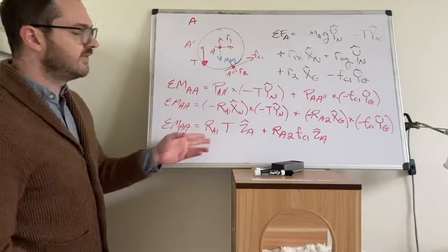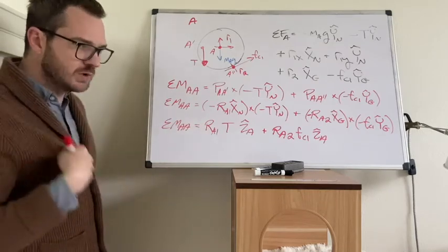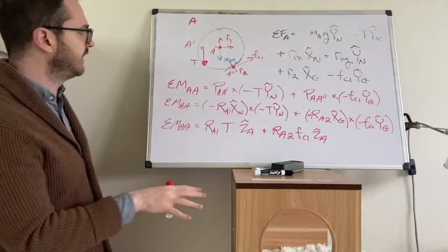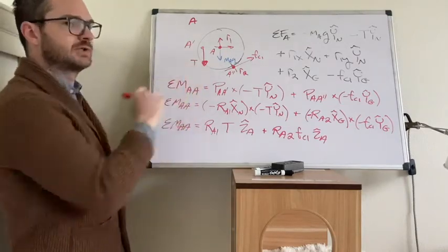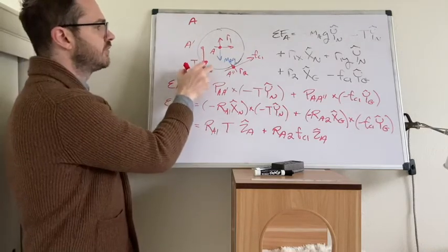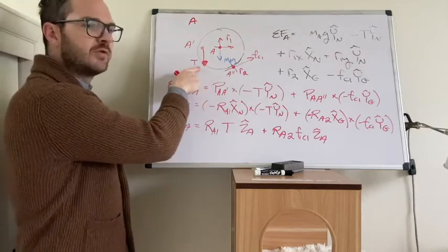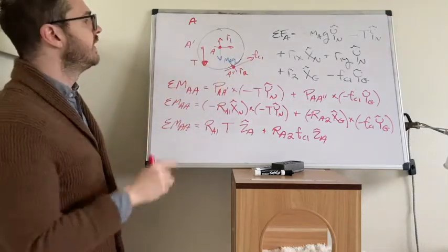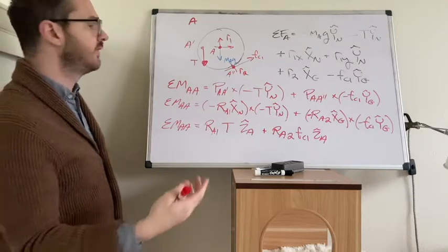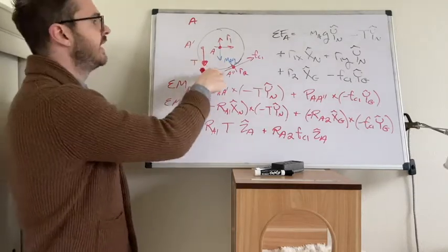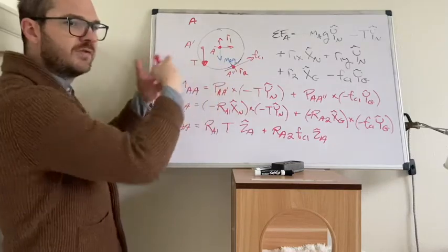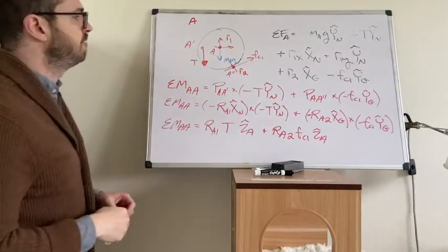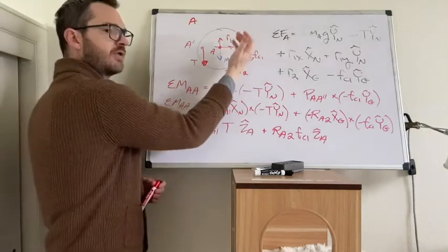Now, does this expression make sense? Let's go back and evaluate it. Let's always take your results and confirm that they make sense. Look at how we drew the picture. The way that we drew the diagram, I assumed a certain direction for the tension, and a certain direction for FC1. If both assumptions are correct, if tension does in fact point down, and if FC1, because of however this thing is moving, does in fact point in this direction, this tension would create a positive moment.